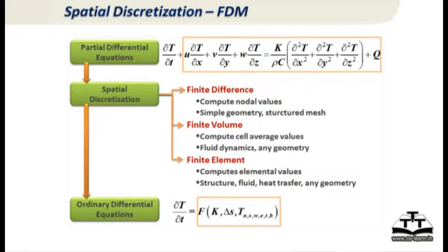In finite volume, which is good also for flow simulation, and we'll come back to this a little later. And FEM, where you can have pyramidal or tetrahedron kinds of divisions, which can be used for stresses also very nicely. So FEM is good for solidification as well as flow as well as stresses, whereas FDM or finite volume is good mainly for solidification and flow.